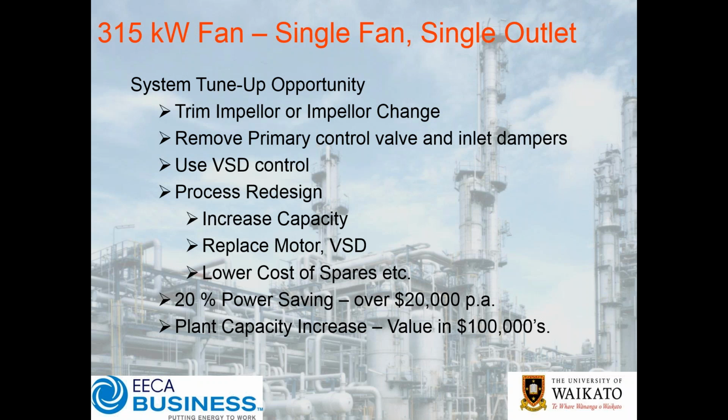Correct. Yeah, so I guess this depends if you're talking about an axial fan versus a centrifugal fan. To be fair, what I'm talking about here in terms of an impeller trim or an impeller change is typically you're still going to stay with the same type of fan. So certainly, with an axial fan, you might have a variable pitch fan which you can adjust, and that's a great means of control.